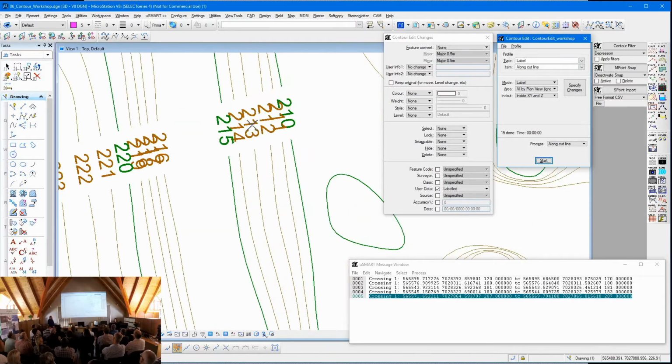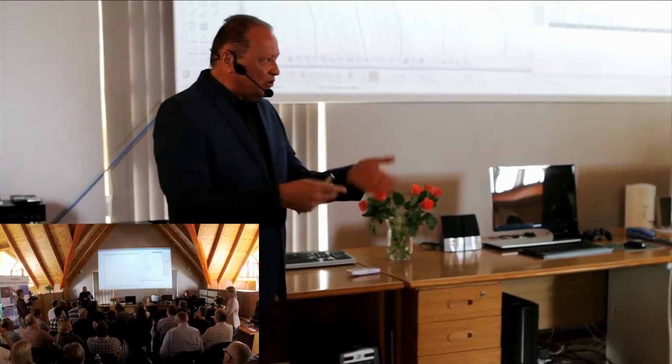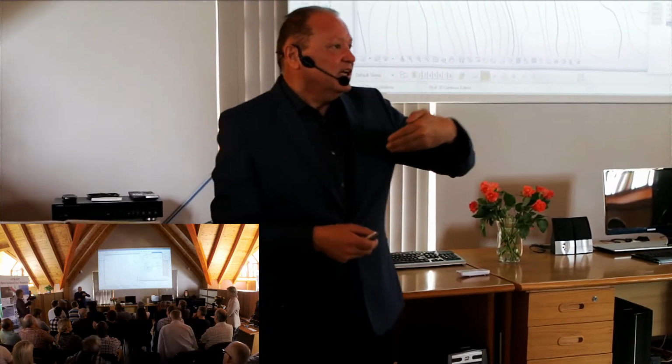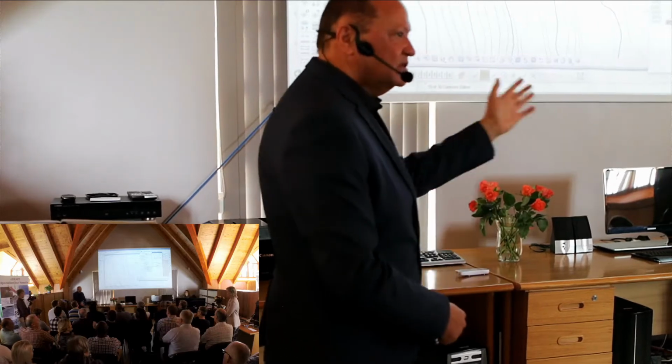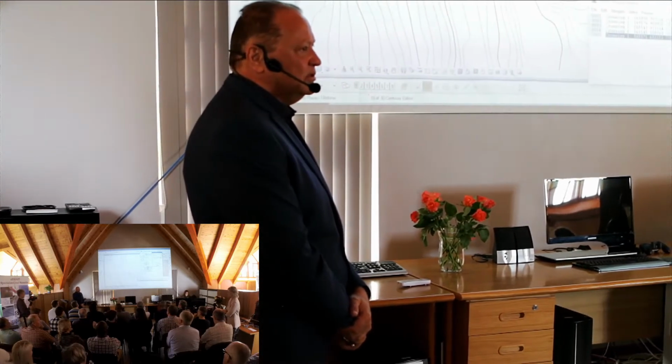Okay, so as it always was. And gaps in the data? If you have contour data that has gaps in it, you mean like a complete break? Like, you mean you're actually going to draw? You're just speaking from a photogrammetric point of view, so you're actually going to add the contours in. Yeah, you can just add the contours, not a problem, and label it as before.